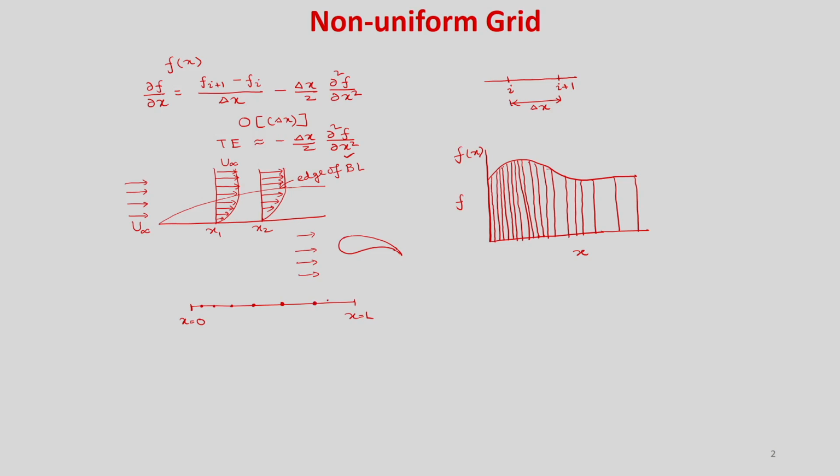Okay. So, you can see it gradually varying. These are the grid points. This is your i equal to 1 and this is your i equal to mi. In a simple way you can find x_i at any point i by x_i / L = ((i - 1) / (mi - 1))^n. You can use this relation to generate a non-uniform grid.